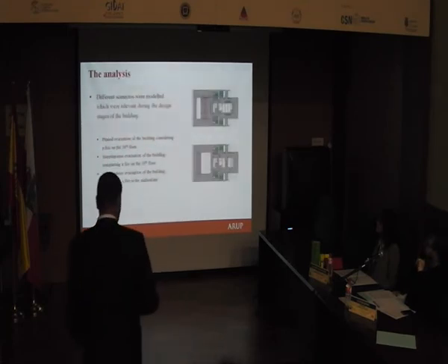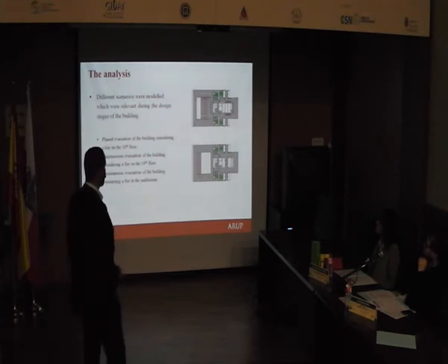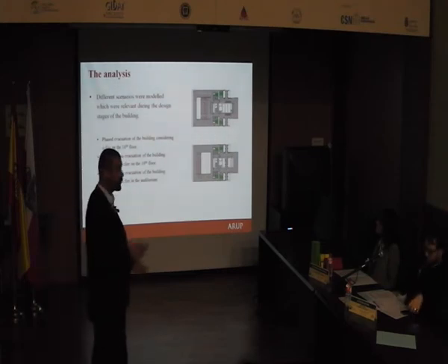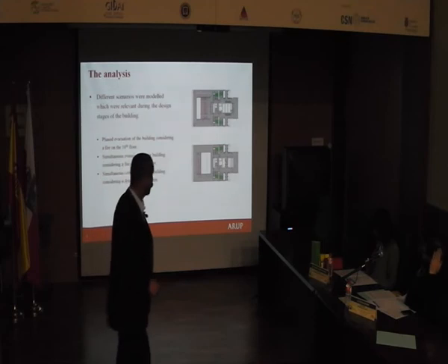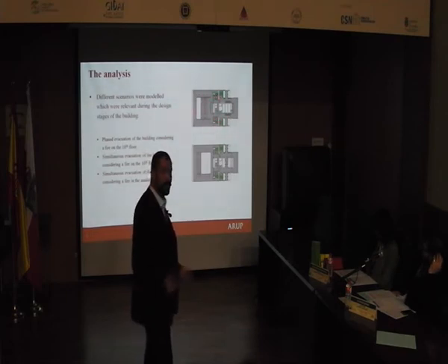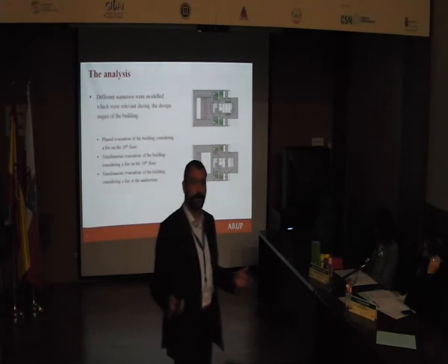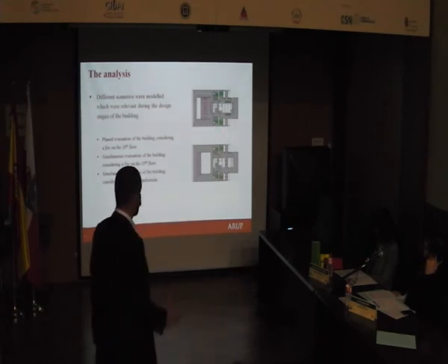We modeled different scenarios. This is part of the auditorium, and we split the auditorium into two different virtual floors. From, let's say, half of the seats the people were supposed to go down, and from the upper level they were supposed to go up. You can see these two stairs that were designed. We suggested including these two stairs just for the auditorium, and then those two stairs are coming from the floors above.